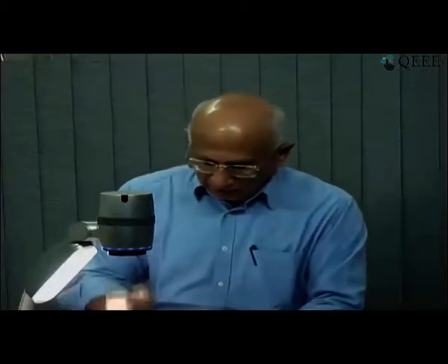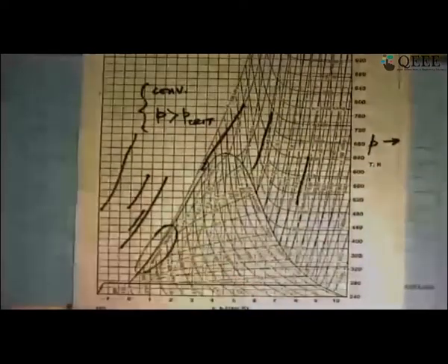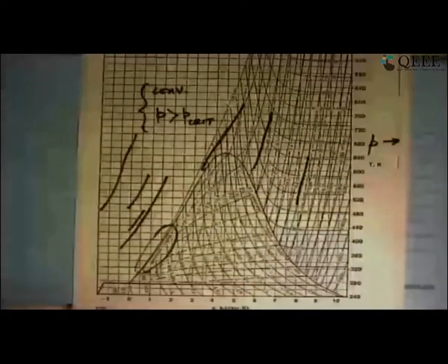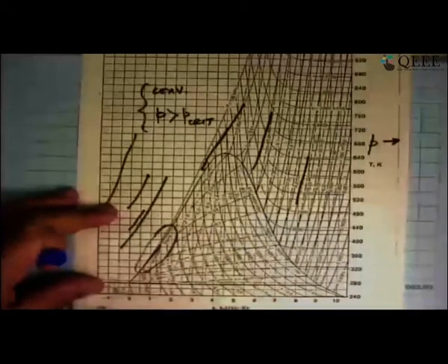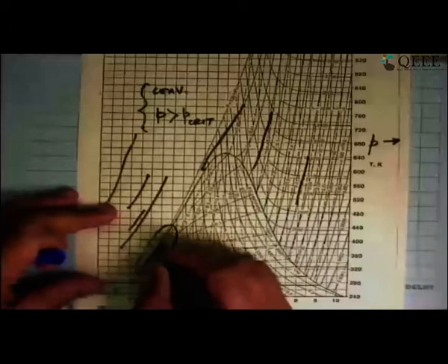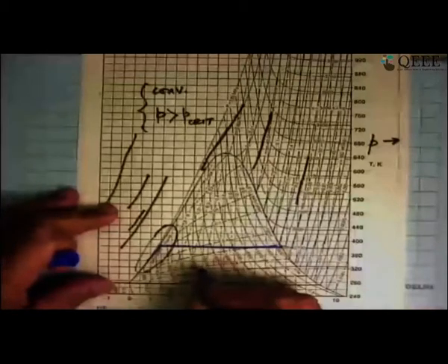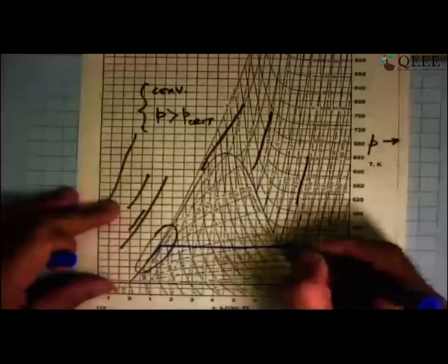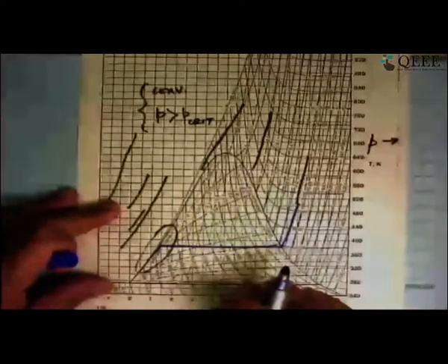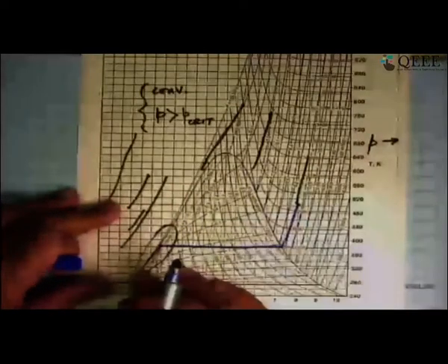So when we design heaters, or condensers, which are below the critical pressure, here is what we end up having to worry about. The process would start here and say we got it up to this point. So this was heating a liquid, which remains a liquid. Then we go that way, converting the saturated liquid to saturated vapor, and then we go there to produce a superheated vapor. And the opposite would happen if you were doing cooling.